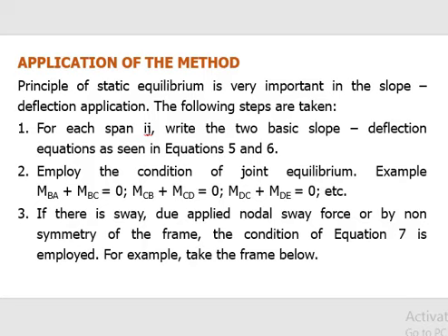Application of the method. The principle of static equilibrium is very important in the slope deflection application. The following steps are taken. 1. For each span ij, write the two basic slope deflection equations as seen in equations 5 and 6. 2. Employ the condition of joint equilibrium. For example, MBA plus MBC must be 0.